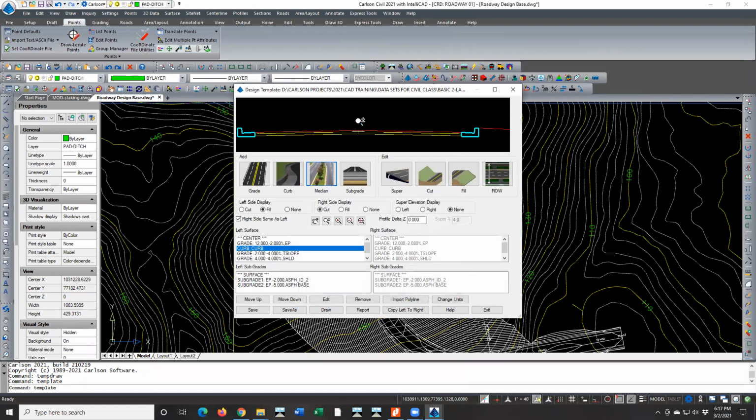So what I typically do is build this road and build that surface, and then I'll draw in plan view the polyline edges that represent the median. Then I'll drape those. I'll do a 2D to 3D polyline by surface and drape it on that surface. I'll do a 3D polyline offset, just a skosh, a half a tenth, and raise it up 6 inches, and bring another one back 6 inches. So that becomes my median.